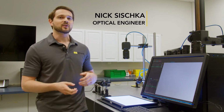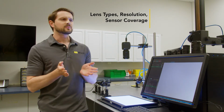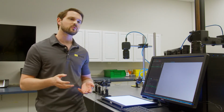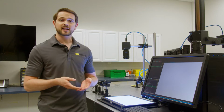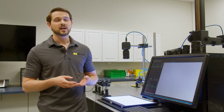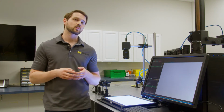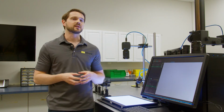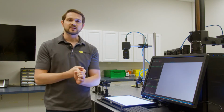If you're just joining us, in our first lab we covered working distance and focal length basics. We talked about the focal length, field of view, and working distance of two different lenses and how their performance compared. The big takeaway from that lab, in case you missed it, is that if you're trying to maximize the performance of your system, you want a working distance to field of view ratio of around 4:1, which means that if you're looking at an object that's about 100 millimeters in size, you want to be about 400 millimeters away. That'll give you optimum system parameters, and make sure your system functions the way you want in terms of costing the least while performing the best.